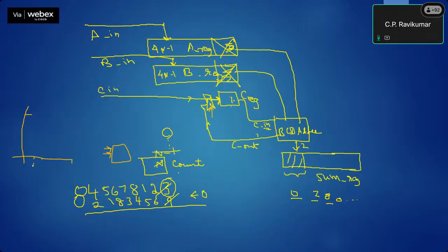So you can take n on the x-axis, and design a 4-bit, let us say this is a 1-digit BCD adder. You have to design with actual gates and see what delay it gives, and as a result what clock frequency you get, and how many clock cycles you take.